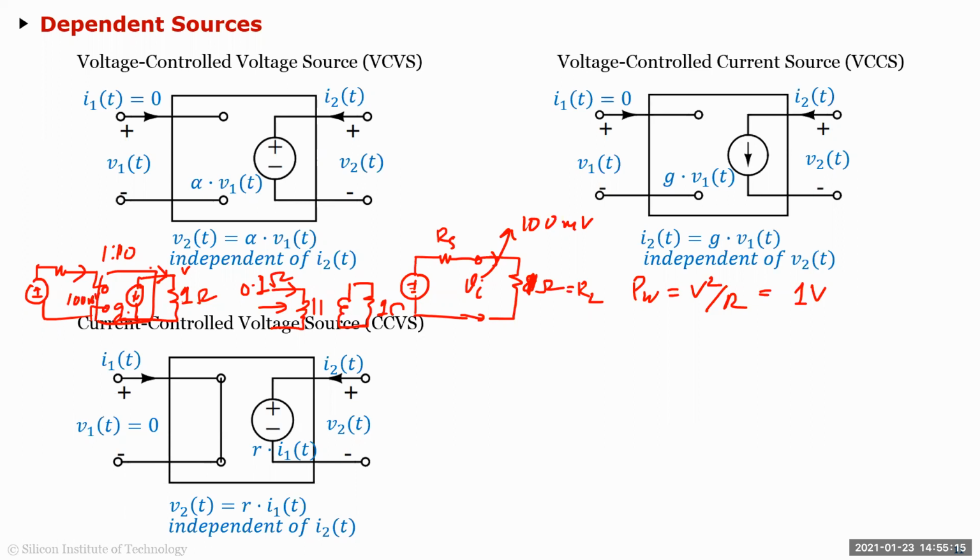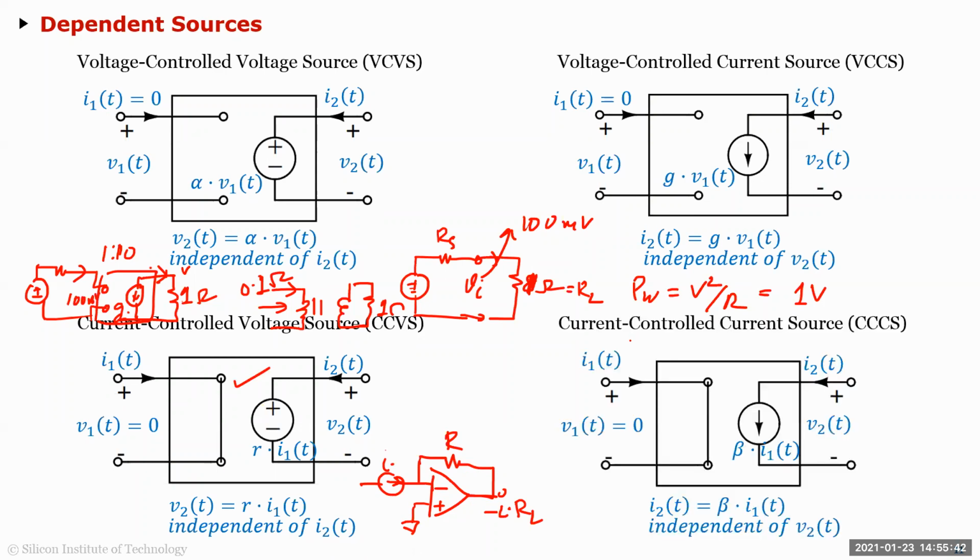So they're very tiny currents. So you take a transimpedance amplifier, and a classic transimpedance amplifier with an op amp is basically just this, right? So your sensor is just providing a current. So let's say this is I. So output is minus I times R, obviously. So you have to invert it, but essentially you get a voltage output. So that's the model for an ideal transimpedance amplifier. And the last one is basically the current controlled current source, where your input is a current, output is also a current. Okay, clear? All right.